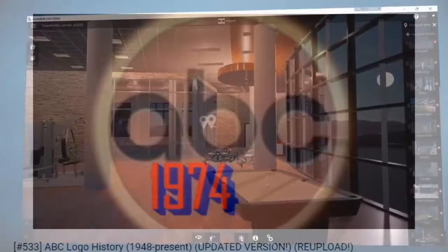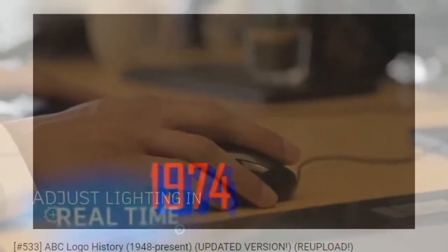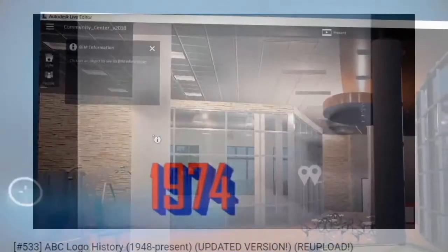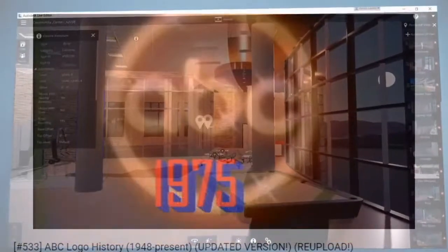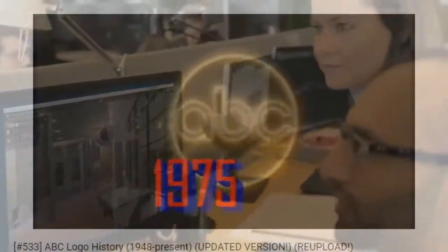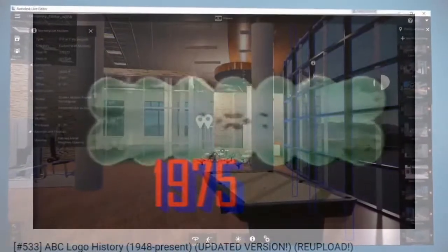Split face and paint tools divide the face of an element, such as a wall, into regions for the application of different materials. The split face tool only splits the selected face of the element. It does not result in multiple segments or change the structure of the element. Paint applies material to the face of an element.